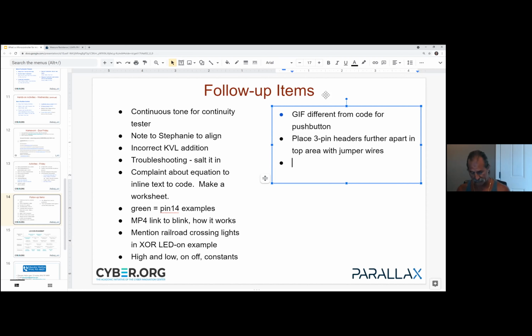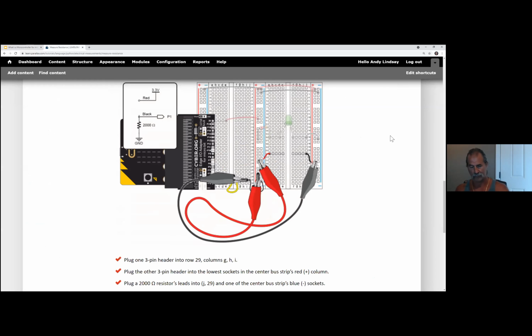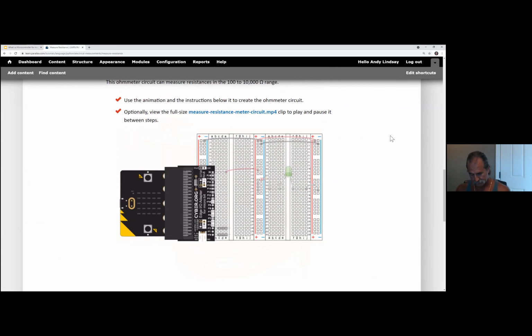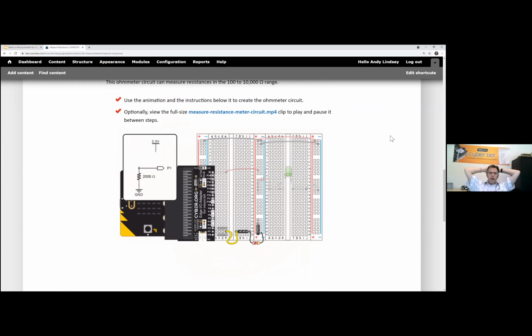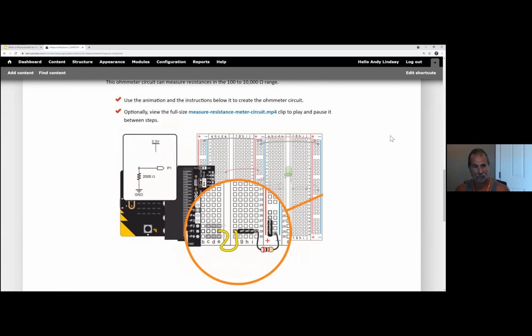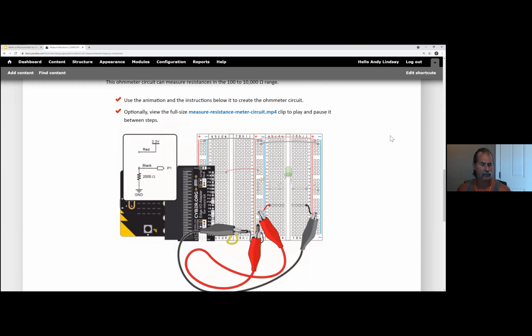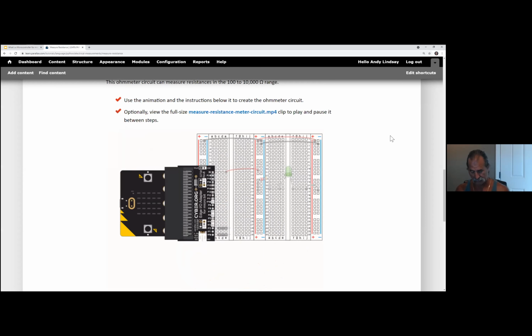But if somebody's saying, hey, I'm having a tough time getting my alligator clip to connect to that without touching, we can start talking, really going back to that definition of the breadboard. How could we move this? How could we still use pin 0 and take advantage or something like that? Yeah, okay. And even though that's jumping over to a different row, you're going from 30 to 29, it's fine. But they could just slide that over the valley and jumper it.